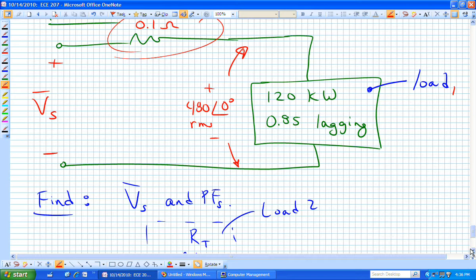What I was trying to do in that second figure was to convince you that if we could figure out what this current is, then we could figure out what this voltage drop is. And once we have that voltage drop, all we really need to do is walk around here, and in so doing, we now have determined what this supply voltage is, because we will know what this drop is, and we were already given what that drop was.